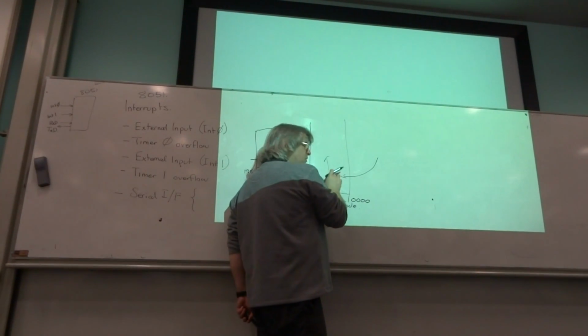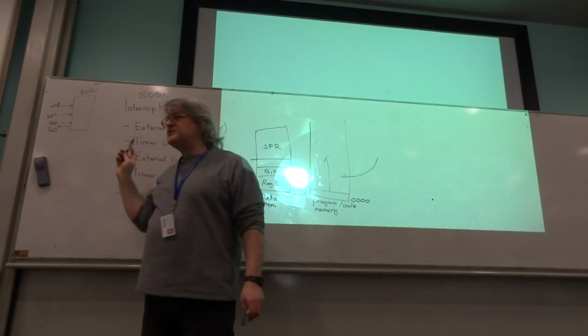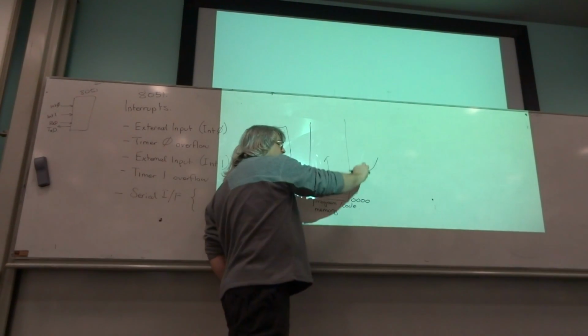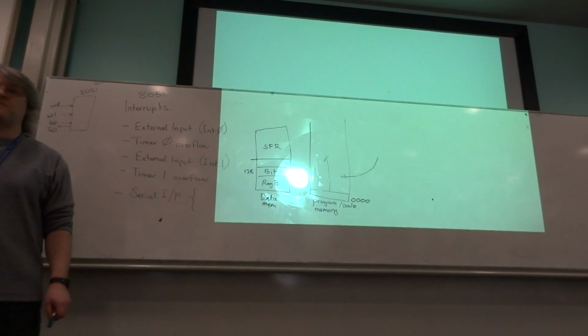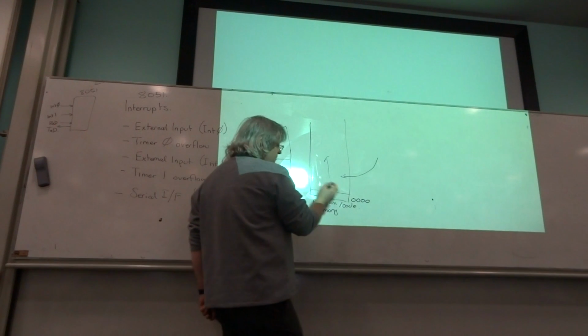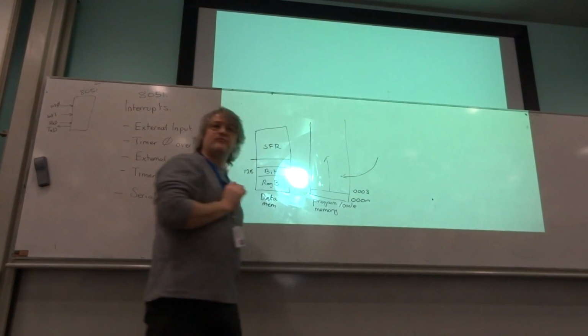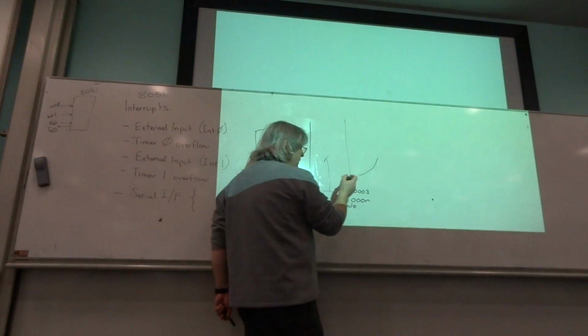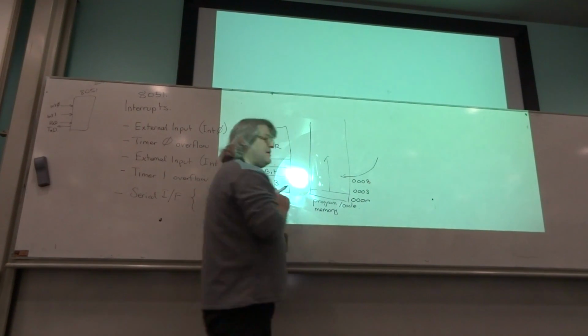So there are special locations within the program memory that the program counter will point to if an interrupt happens, and you will continue executing your code from that point onwards. Now, I don't remember all of them, but one of them, for example, is at location 0003. There's another one at location 000B, and so on.